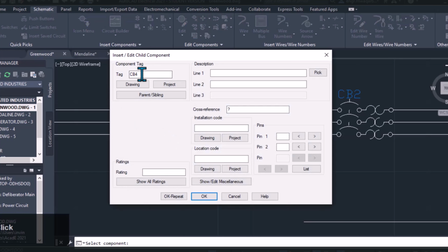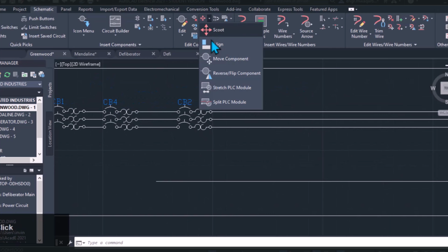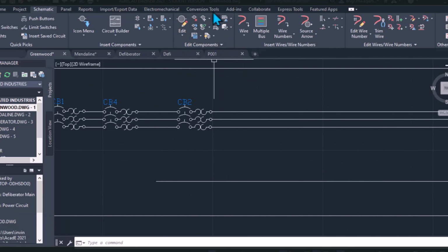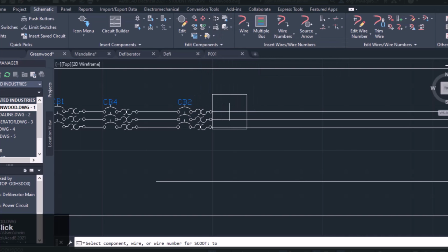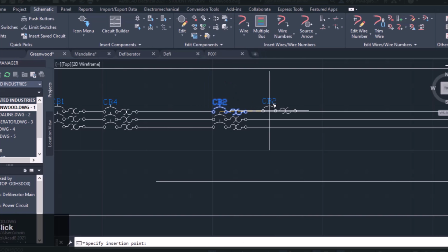If you try to use a basic copy and paste command on the visual shape of a child contact, you're only copying a sibling. You aren't copying the main brains of the operation. No, you're just drawing a meaningless shape. Exactly. You have to explicitly dive into the database and link new parts back to a specific parent so the software knows they physically actuate together.